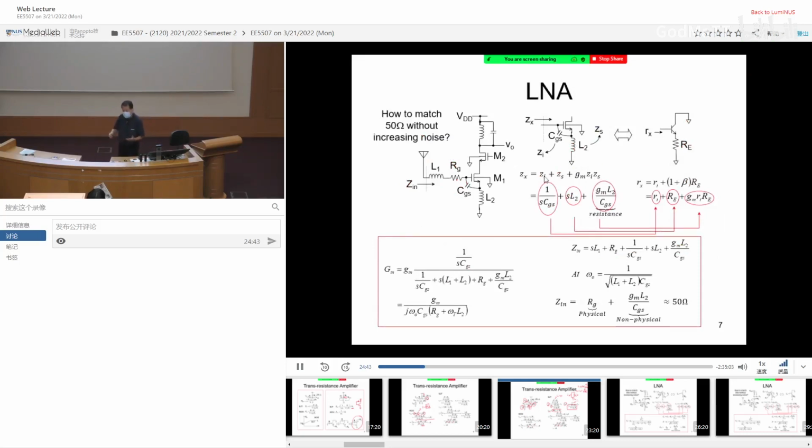And you'll probably say, why not use the op-amp? Minus A, I can use the op-amp to create the gain. Now remember this, when we talk about optical, these are very high frequency. We are talking about hundreds of gigahertz. Okay? So op-amp is usually limited to what frequency? 100 megahertz. Right? So therefore, you can only use very simple structure, single transistor amplifier, so on and so forth. And then you feed it back. Otherwise, the parasitics are going to kill everything. Okay? So for optical amplifier, that is very high frequency, that is what we do.